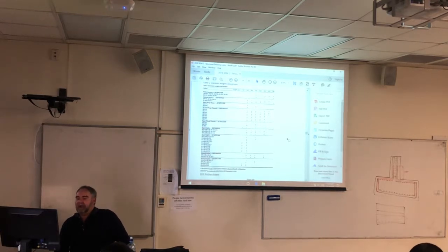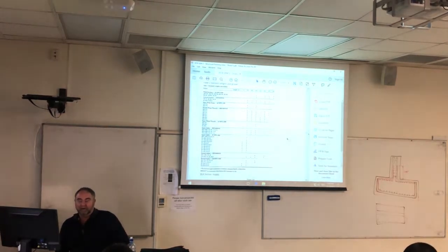If I was to make that part of your assignment, you'll notice that 13.5 is a popular length, and we've made our bridge 13.2. So maybe you would think seriously about making the bridge just a little bit longer, because that's the size member that they produce in the factory.